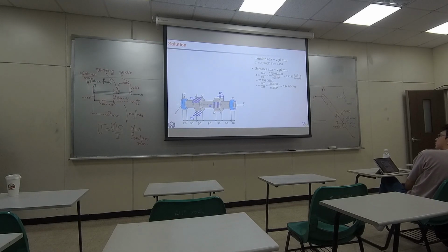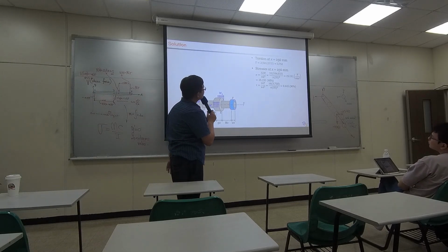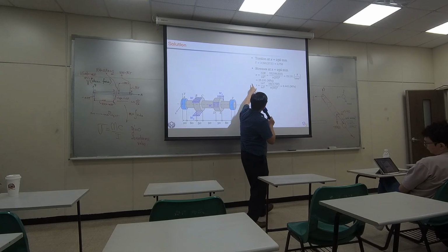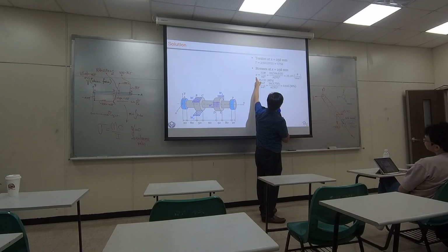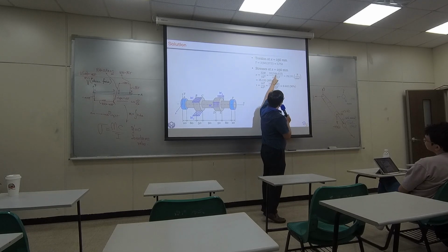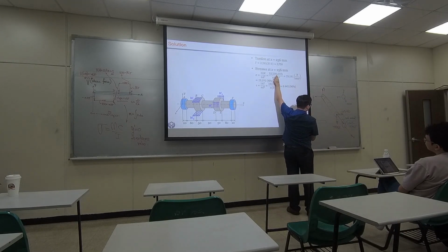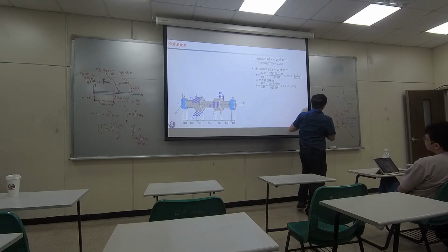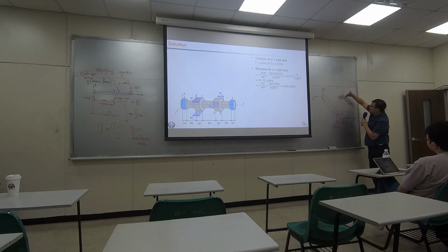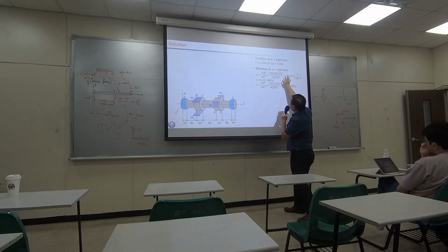To study the stress, at that worst loading position, if you want to compute the stress, you need to use the total moment. So I'm actually using the total moment. 32 times total moment over pi d cubed. This is a true stress. But the stress is along some angular direction. So this is how you compute stress.